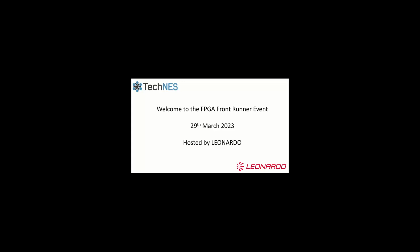So if we flip to the next slide, the other obvious one is MATLAB code. So you can do VHDL without code generation straight from MATLAB. It's not something I really recommend in general. Primarily, it's not that much less verbose than VHDL, really. You've got to manage your fixed point data types just as manually. You've got to control bit growth, saturation and wrapping, logic, that sort of thing. It's all controllable, but it's a lot more hidden from you.